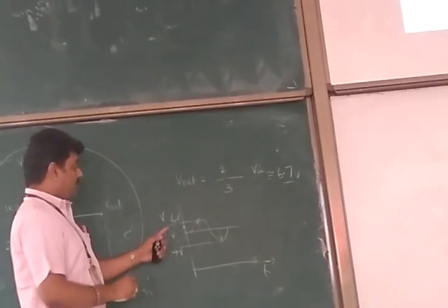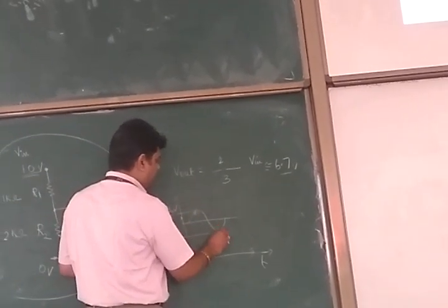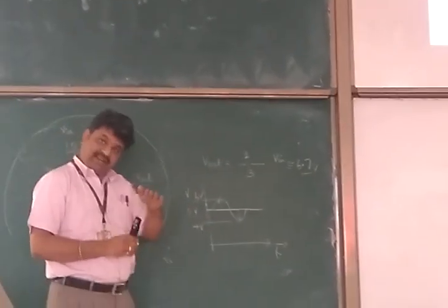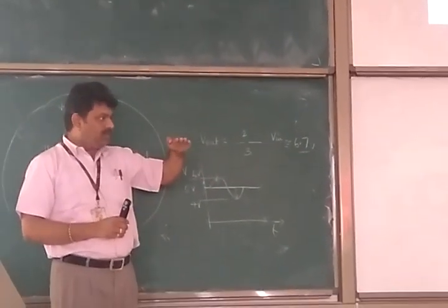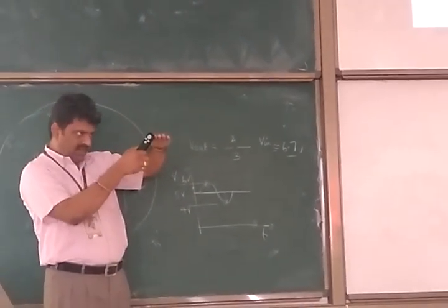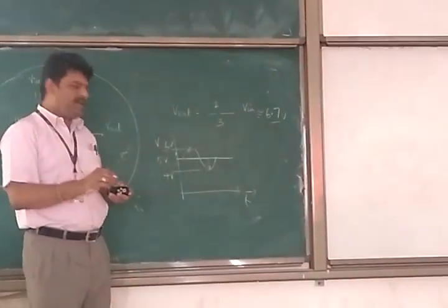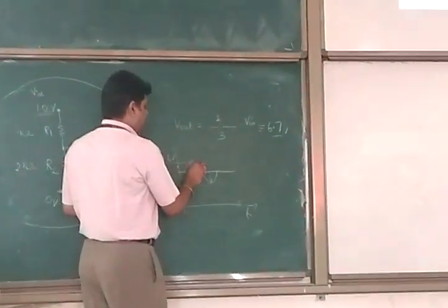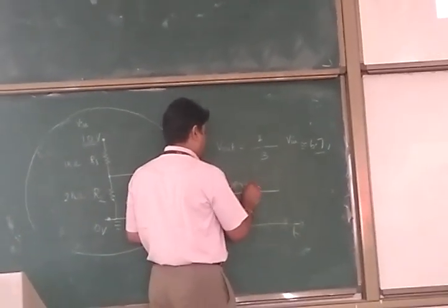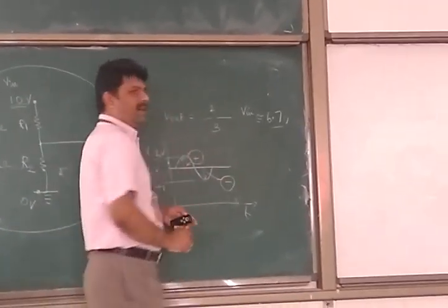Okay. So what I do is, I have some sinusoidal variation. I will use some middle voltage as my reference voltage, above which my input signal will go slightly above, come to my reference voltage, come below, and then below. So that the variation above my mean voltage, below my mean voltage, this is positive, representing all positive values. This is representing all my negative values.